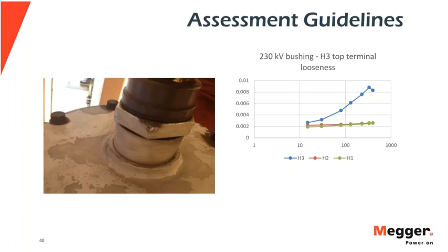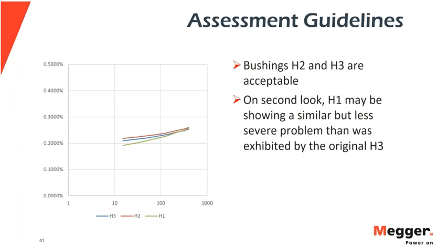So in this case, it turned out to be a loose top terminal on the bushing. You can see a really zoomed in picture here on the left-hand side, where there's actually some discoloration at the terminal. This is the top cover of the bushing, bolted down; the site glass would be underneath this. You can see where that discoloration takes place. Interestingly, when they tightened this terminal up properly, the bushing tested perfectly afterwards, but the decision was made to